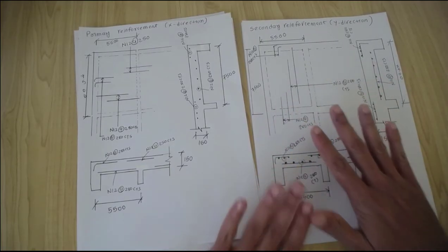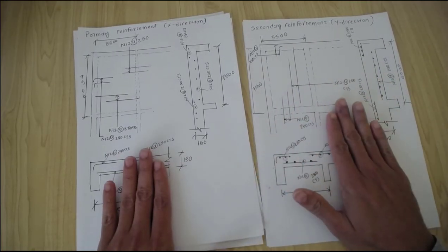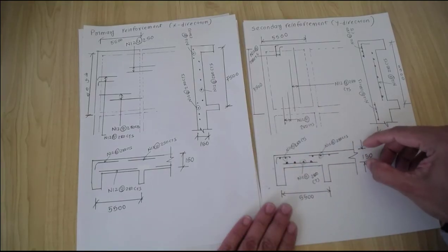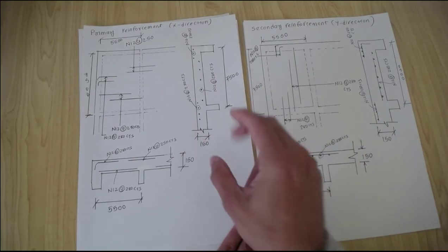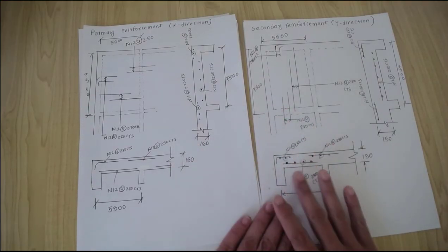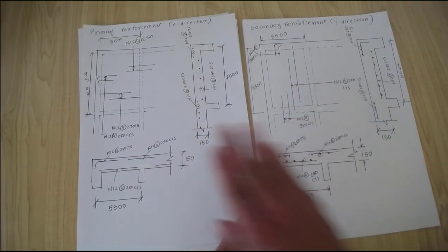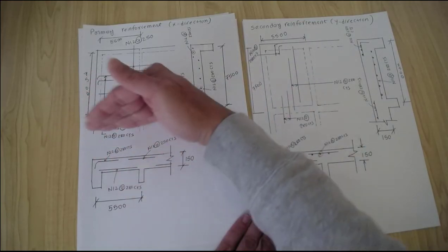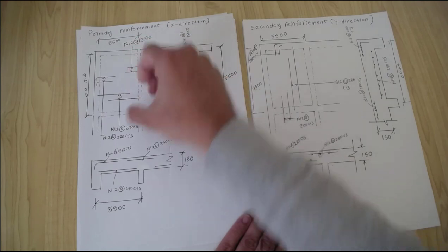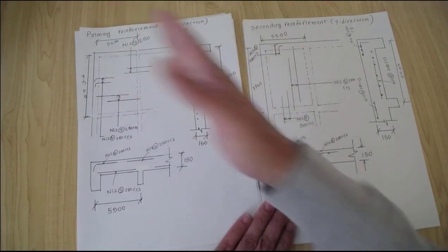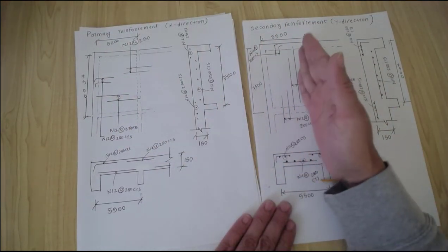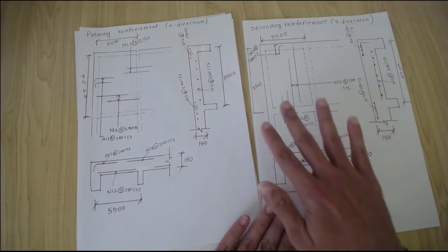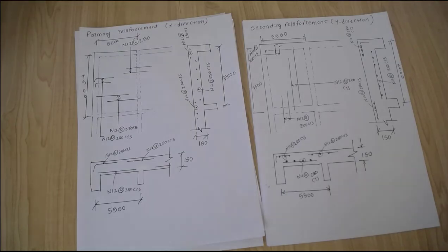So I think this is the primary and secondary reinforcement detailing, and it has all the details. The depth of the slab is also indicated, 150 millimeters for each. So that is the final step. We did the detailing in the primary X direction and secondary Y direction. Please note, primary direction is along the short edge, so we provide this reinforcement here. This is the long edge, and we provide the secondary reinforcement along the long edge, and we found the center to center distance for each location.